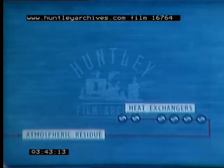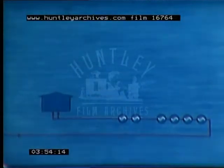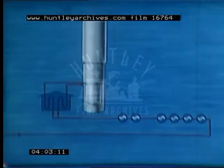Building up a flow diagram, we start with the feed, in this case, atmospheric residue. After initial heating in the heat exchangers, the flow is split so that the incoming residue passes through a fired heater. Even under reduced pressure, the atmospheric residue requires a great deal of heating before it boils. The partly vaporized oil is carried from the heater into the tower in several large diameter pipes. It enters above the 7th tray.